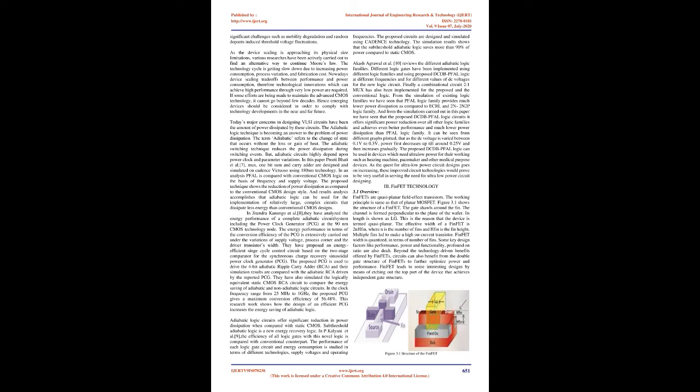Independent control of front and back gate in double-gate (DG) devices can be used to merge parallel transistors in non-critical paths. This reduces the effect of switching capacitance and, hence, the dynamic power dissipation of a circuit. However, efficient design of large-scale circuits with DG devices is not well explored due to lack of proper modeling and large-scale design simulation tools. Agarwal et al. [4] proposed several low-power circuit options using independent gate FinFETs. They developed semi-analytical models for different FinFET logic gates to predict their performance. An efficient circuit synthesis methodology comprised of the proposed low-power logic options in a FinFET design library has been developed. Results show about 8.5% area savings and 18% power savings over conventional FinFET technology for ISCAS85 benchmark circuits in 45 nm technology with no performance penalty.